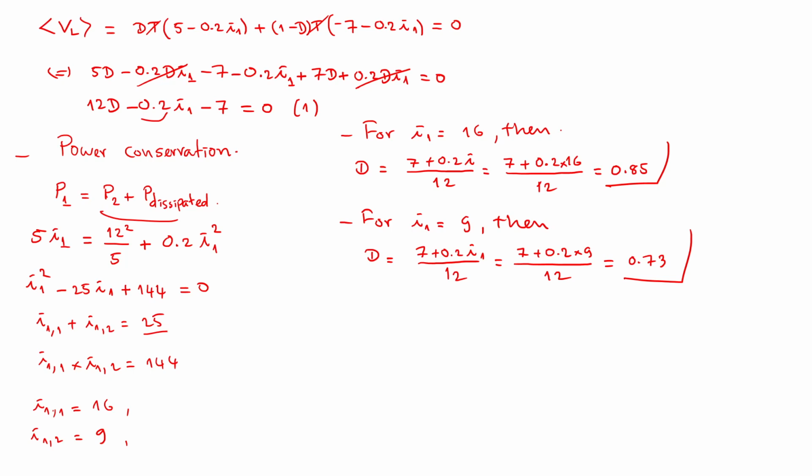Yeah, for sure, in any case, your boost converter will operate normally. Just, sometimes we want to save power a little bit. So it's the second one. Why? Because we bring the value of I to substitute in the equation of D, and D is related to the voltage, the VF.